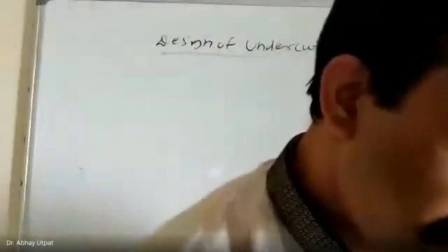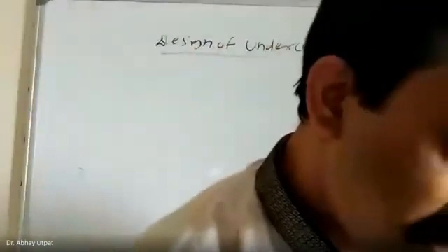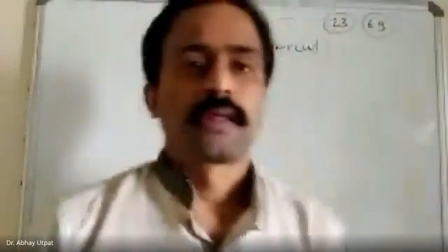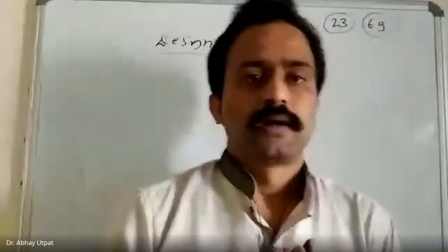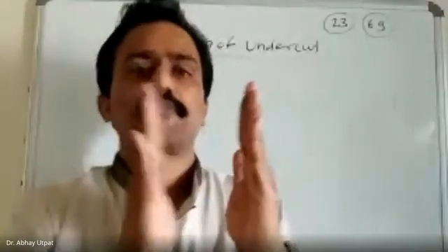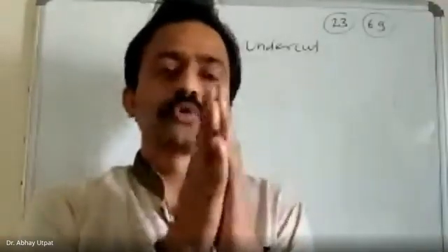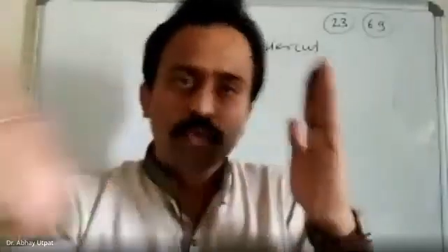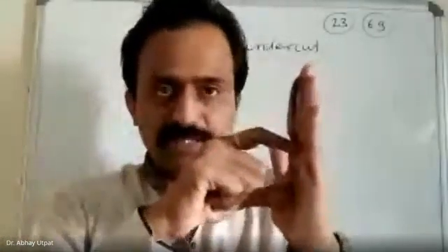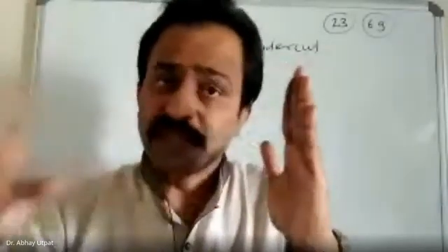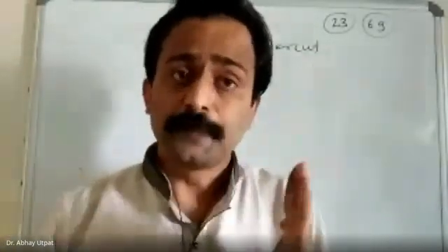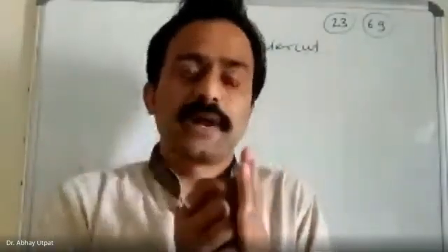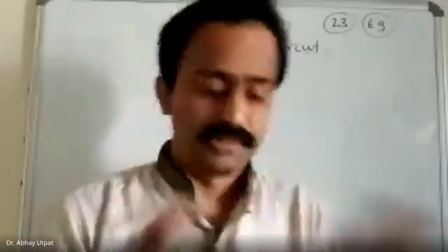Okay, so if this is one of the mold halves, and this is another mold half, you are going to close this mold. The component is inside. If you open it, the product which is here, you are going to remove by ejector pins. If it is having an undercut, it means some extended part which gets locked in the mold.